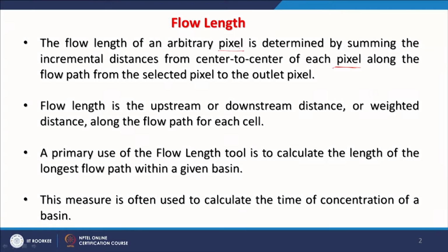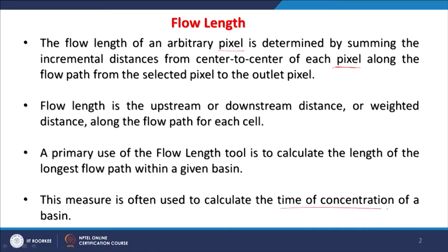We can determine that through this step in surface hydrologic modeling, and flow length is often used to calculate the time of concentration of a basin, which is directly linked with flood forecasting. It may also be related with sediment flow or some other pollutants, because this is after all the time of concentration, how much time it would take to reach a particular location.